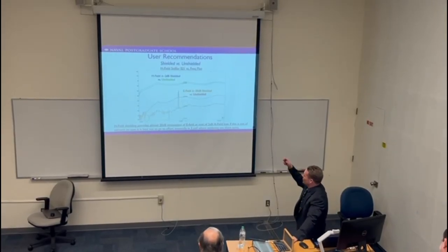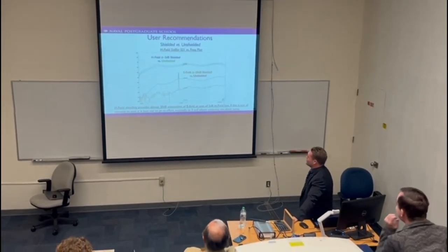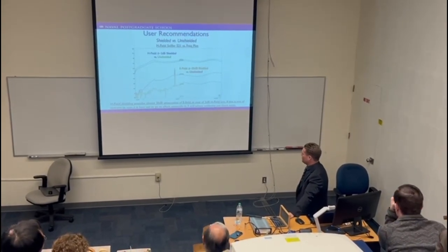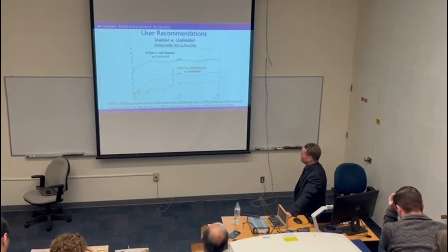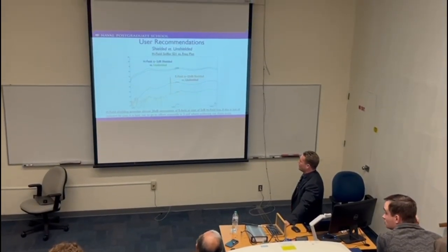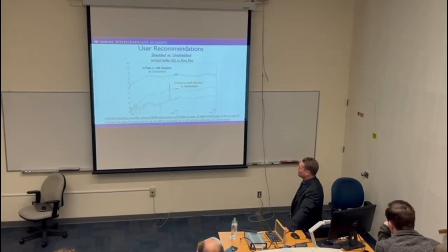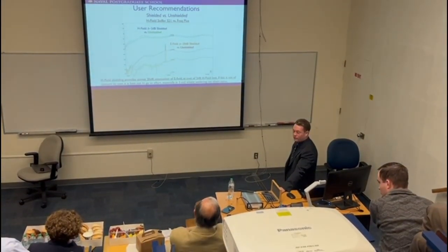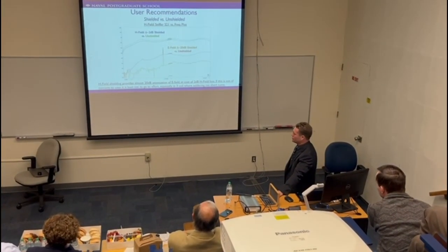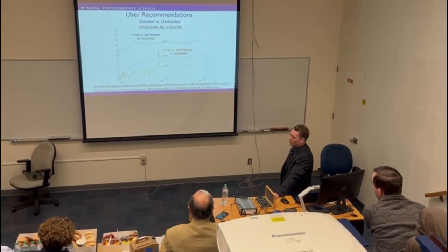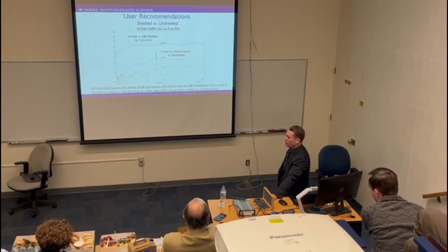So here again, shielded versus unshielded. 20 dB attenuation of E field. I would say that there's little advantage to not having a shielded system, other than when you're doing a 3 coil and you're soldering, like I was mentioning with the originator, it's a lot more difficult to solder when you have 3 coils. You can literally melt the coils together. So that's one of the only downsides I can think of when you're using the shielding.